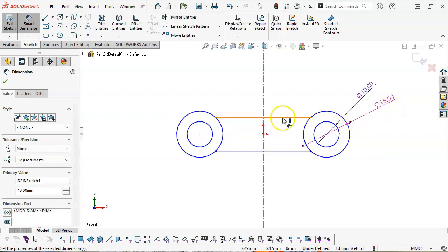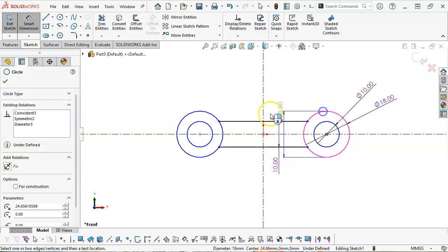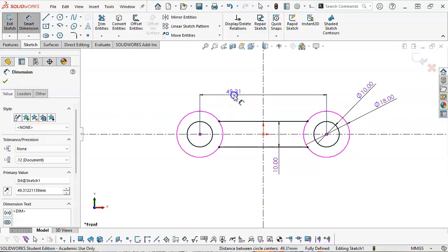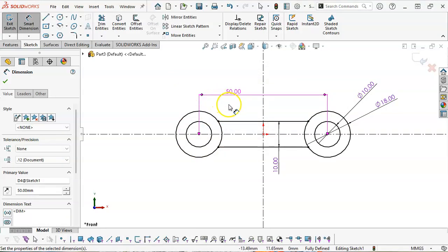In previous videos where we've seen this type of geometry, I always make the point that from a manufacturing standpoint, we're not necessarily gaining a whole lot by doing the dog bone configuration. If there's a clearance issue, maybe, but realistically, from my manufacturing standpoint, if I really needed to lighten this, I would rather have an oblong round with a slot through the middle and the holes at each end. All right, but again, personal preference, easier to machine than trying to make the cuts.